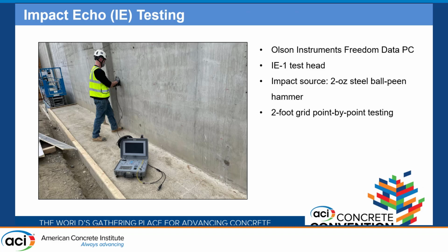For the impact echo testing, again, we used the Olson Instruments Freedom Data PC. Because we did point by point, we used an IE1 test head and a 2-ounce ball peen hammer as an impact source. And we did a 2-foot grid across the entire wall.